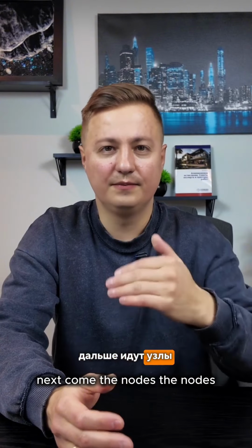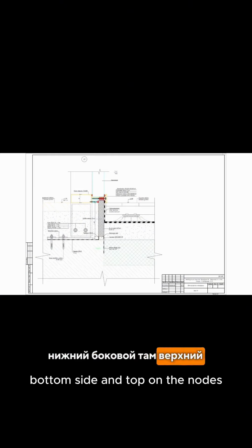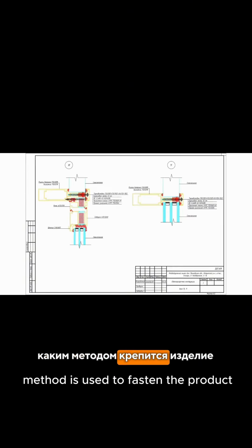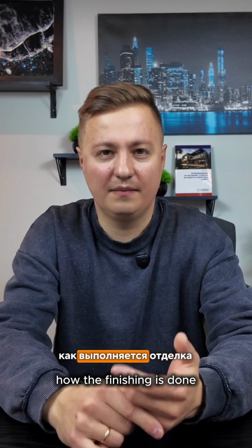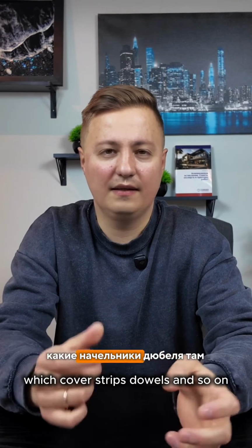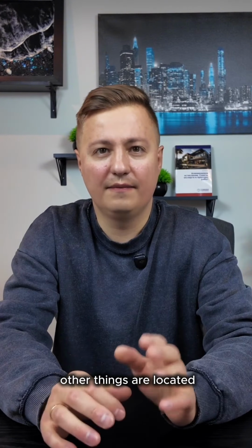Next come the nodes. The nodes, accordingly, are also horizontal, bottom, side, and top. On the nodes, it is shown, accordingly, which method is used to fasten the product, what materials are used for fastening, how the finishing is done, with which materials, where the sandwich foam is, which cover strips, dowels, and so on, where the steels, tapes, and other things are located.